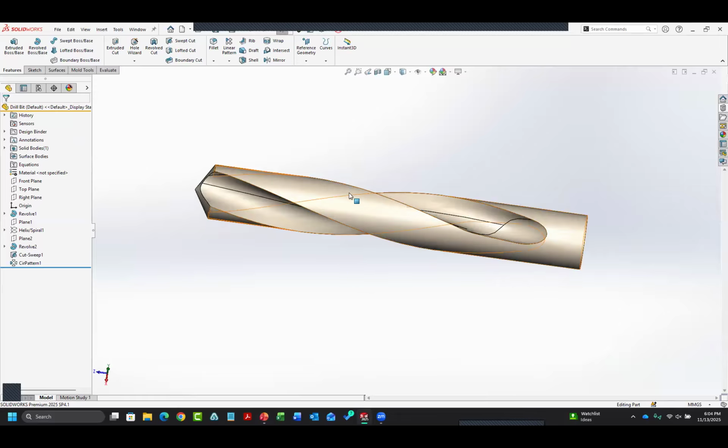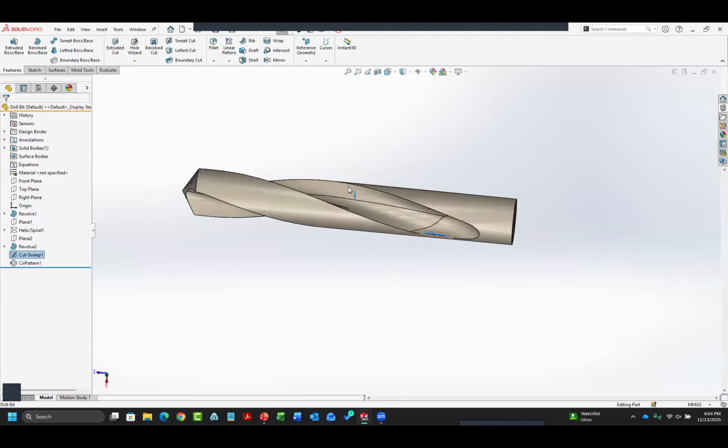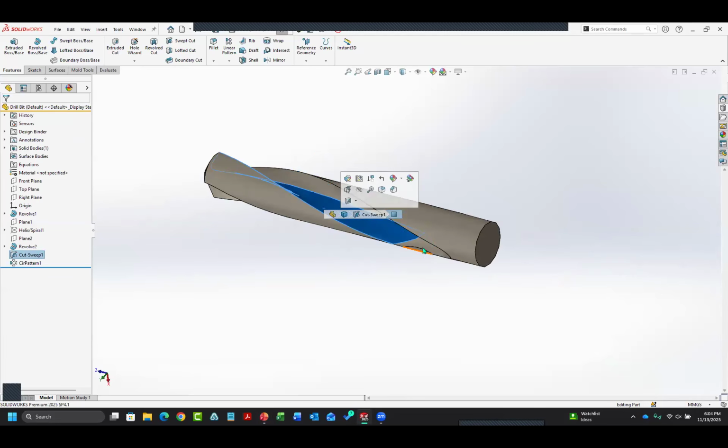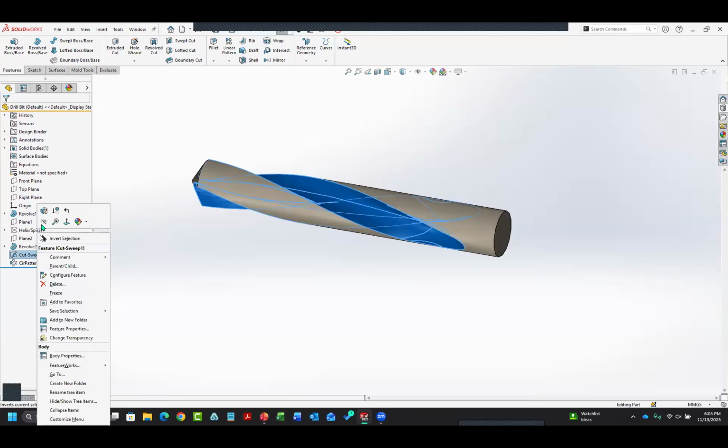And we have this example. As I mentioned, we have a couple of things. One is these little tiny faces. There's a couple of them here. There's also these faces that have been segmented out. Now, a lot of times we may not realize why this happens inside of SolidWorks or any other CAD model. A lot of times it has to do with how something was made or how something was sketched. If you sketch something, usually wherever there is a point, you could introduce an additional seam or it splits the face. That's something to keep in mind.